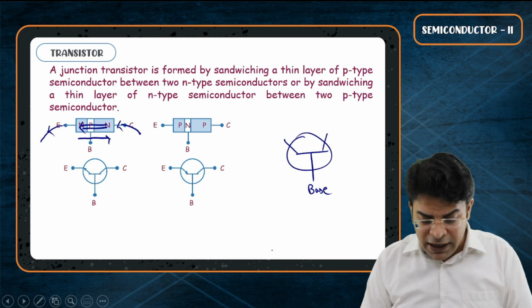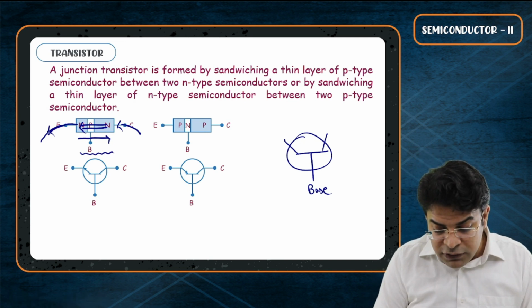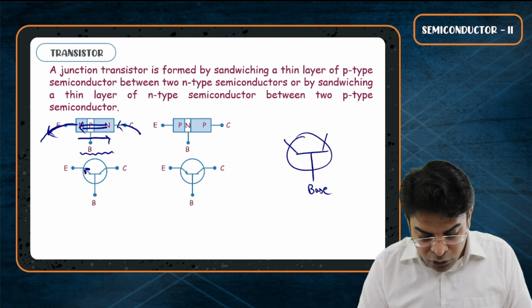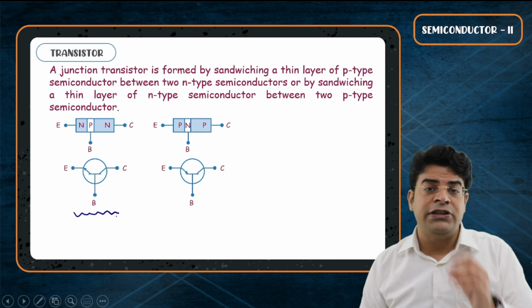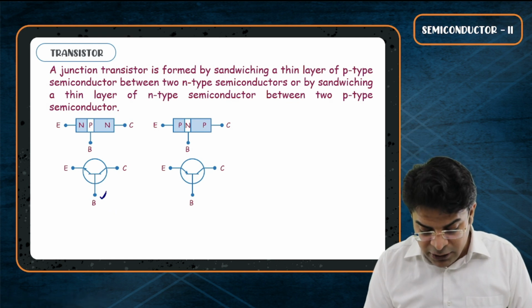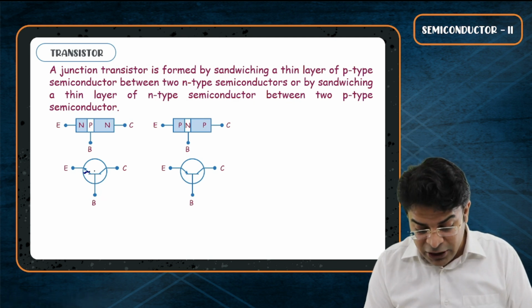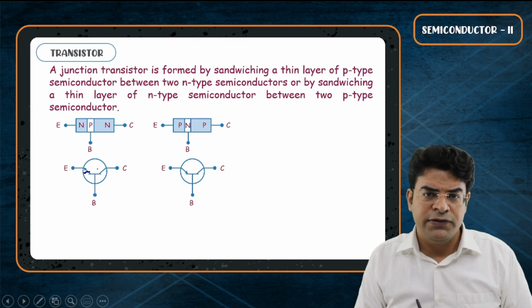If you have an NPN transistor, then current comes out of the emitter into the circuit. So that's why current is marked coming out of the emitter. Do remember, when we use the circuit representation, the one trapped in the middle is the base. The one on which current is marked is the emitter, because it's the job of the emitter to emit majority charge carriers.